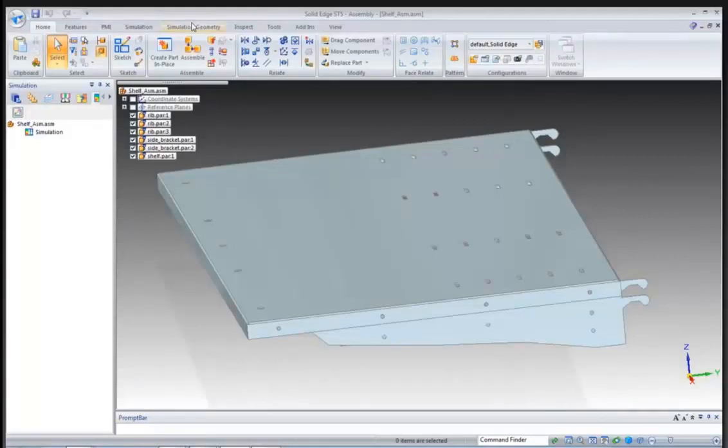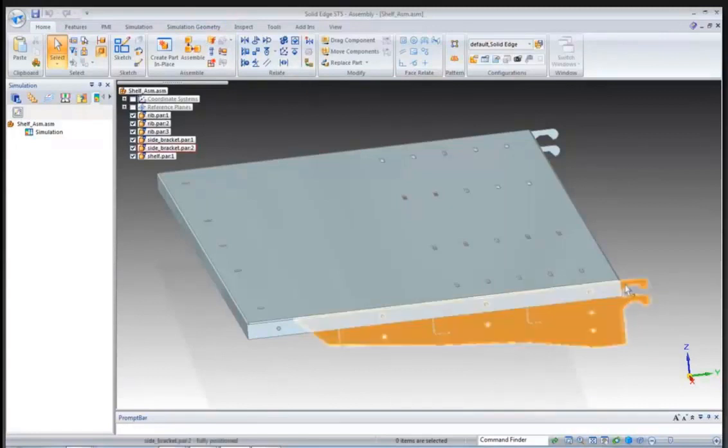I see so many times people just throw something in and see what they get. You know, that's not what this tool is meant to do. That's not what any finite element analysis tool is meant to do. You have to be very specific in what you're looking for, and the reason for that is because we make simplifications along the way.